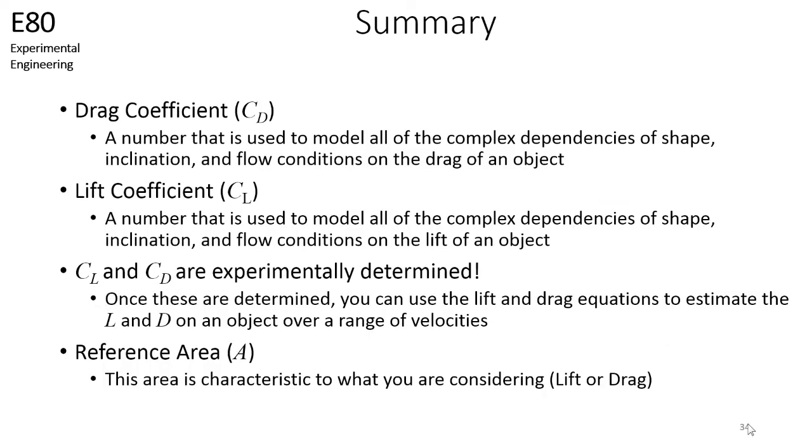This video focused on the drag and lift coefficients. These coefficients can be determined experimentally and enable the lift and drag forces of an object to be determined without having to carry out complex integrations. However, correct calculations of lift and drag depend on using the appropriate reference area. Frontal area is typically used for the calculation of the drag coefficient and drag force, while the area that is relevant to the generation of lift is used for the calculation of lift coefficient and lift force. Be very careful when choosing your reference area.